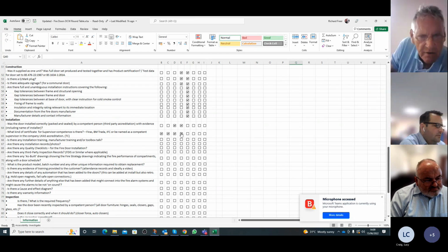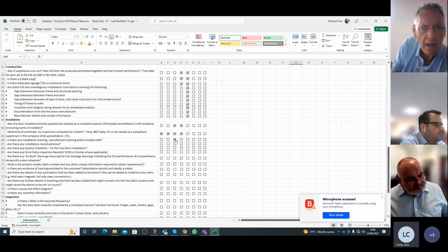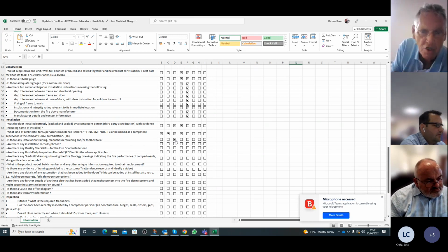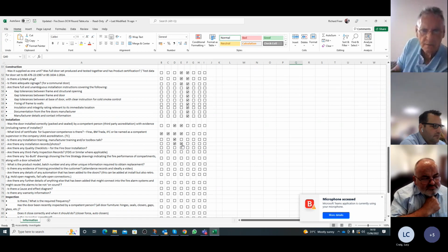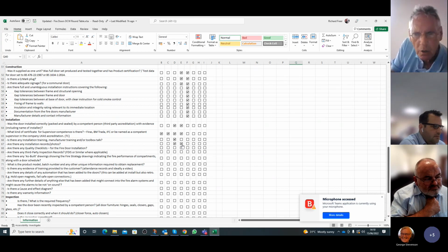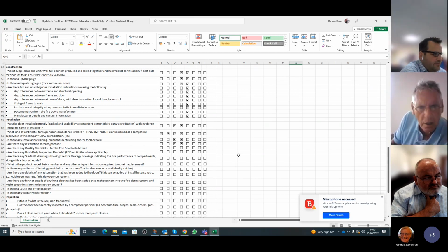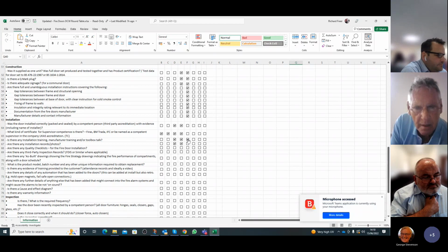Okay. Is there any installation training, manufacturer training, and/or toolbox talk? Who would be responsible for that? Well, that would be main contractor and installer. Photos of installation, or making sure there are photos of the installation. Again, main contractor and installer, because the main contractor should be insisting on where that's stored. But the installation training, that's the manufacturer, because the manufacturer sets the installation guideline for that door. It has to be installed in a certain way. Yeah, absolutely.